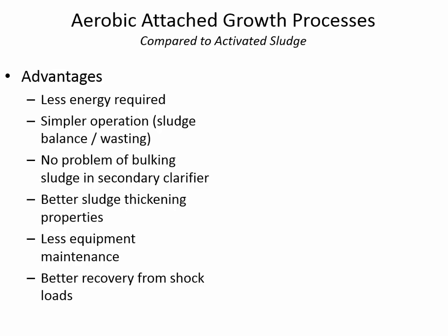And that's about the scale of improvement one can get with a good settling sludge, like you'll see with suspended growth, is better sludge thickening, and therefore it's less expensive to get rid of the sludge. Shock loads is another thing. We've talked about how a shock load is suddenly there's a huge pulse of BOD, or maybe there could be a toxic substance from an industrial wastewater that gets discharged into the waste stream.